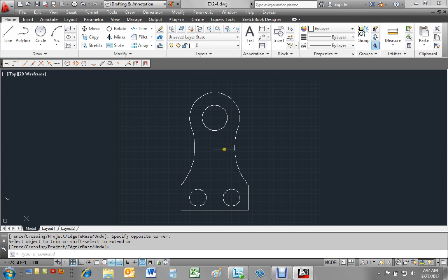Okay, here we are back at exercise 2-4, part 3 demonstration. Now we're going to create this inside shape that you see in the problem on page 2-31 in your textbook. The arc we just created here and here has the same center as the arc we want to create in here. I've determined that by adding 3.5 inches radius to the outside radius, which was 5.